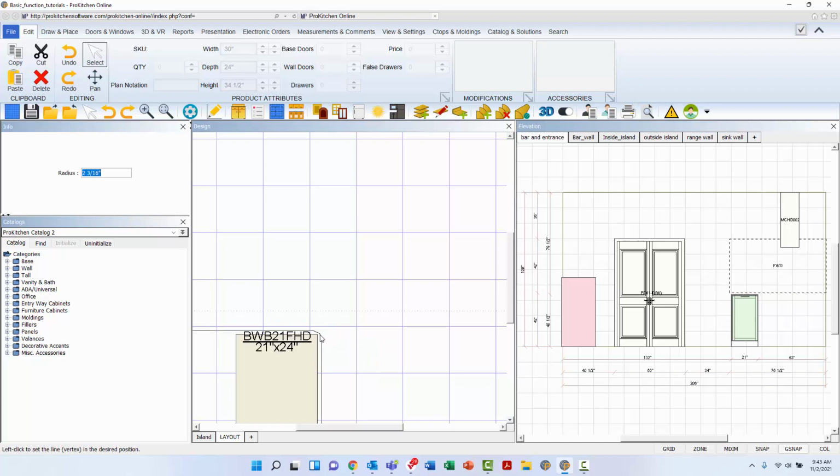Back in the additional right-click toolbox for a point, we will find Bevel. Again, once selected, you may only make this edit toward the interior of the countertop. This time, an angled line will appear that will essentially cut the corner off and provide a smooth, straight line in its place. Once the beveled edge is in the desired location, left-click to secure. There will then be an additional 2 points and a single line in which you may select and continue creating edits.